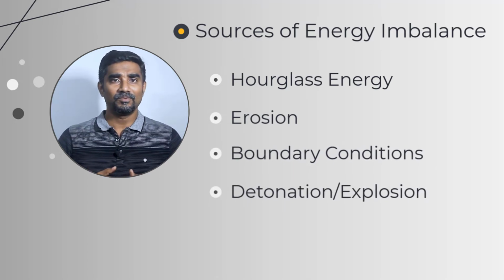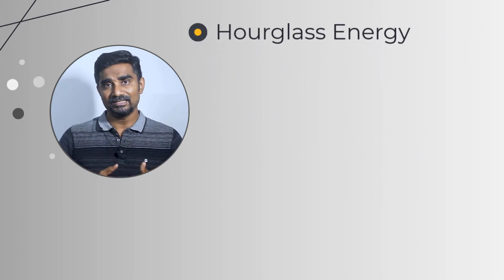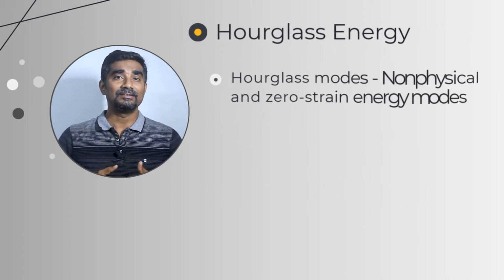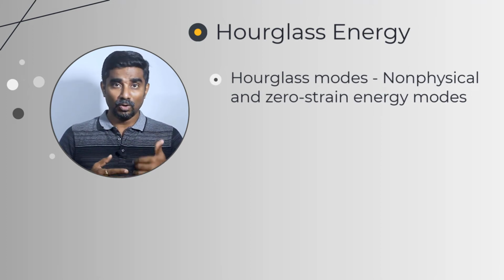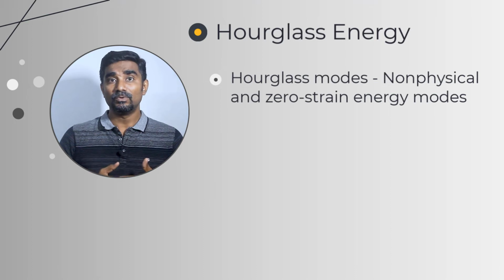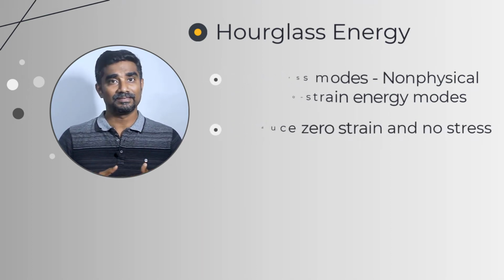Let us discuss some of them and see how they affect the overall analysis. The first source is the hourglass energy. This type of energy imbalance is caused by the hourglass modes, which are non-physical, zero energy modes of deformation, and they produce zero strain and no stress.